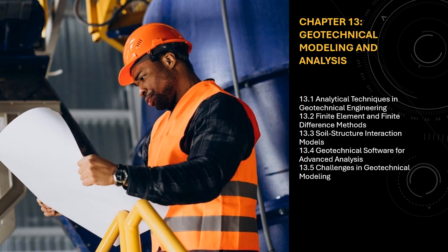3.3.2.1 Simplified or Winkler Model, Spring Model. The Winkler model is one of the simplest ways to model soil structure interaction. In this approach, the foundation soil is represented as a series of independent springs, each spring representing the soil stiffness at a point. This model assumes that the displacement of the structure causes an elastic reaction from the soil at each point of contact.